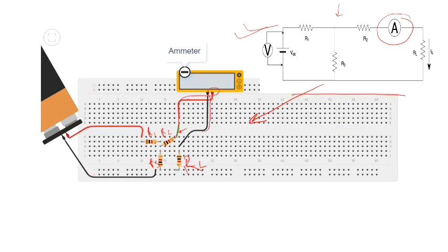So the flow of current would be somewhat like this, meaning that current would travel through the ammeter giving us its value, and we'll be able to identify the value of IL in the complex circuit. Now the next step would be to identify IL in the equivalent circuit. But before doing that, we need to find out VTH and RTH.